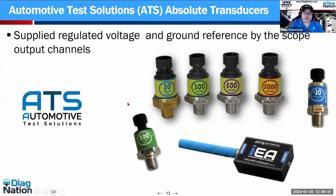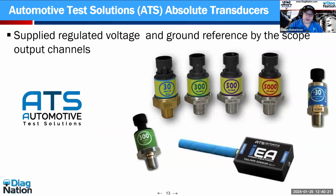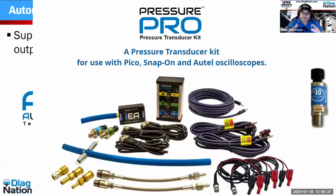All right. So here's just a few pictures. Here's some Automotive Test Solutions, many of which can be found through many, many manufacturers like this. Once again, they require an external power source. Here is the Pressure Pro. This is a kit that Automotive Test Solutions puts together that allows you to use the proprietary power interface. That's right. This box, through these cables, powers these up so they work, and then you can run this into any lab scope. So instead of being stuck in this case to having these transducers as an example only for the Automotive Test Solution scope, Bernie and the boys put together this kit so we can hook it up to our Picos, our Snap-ons, or Autels.